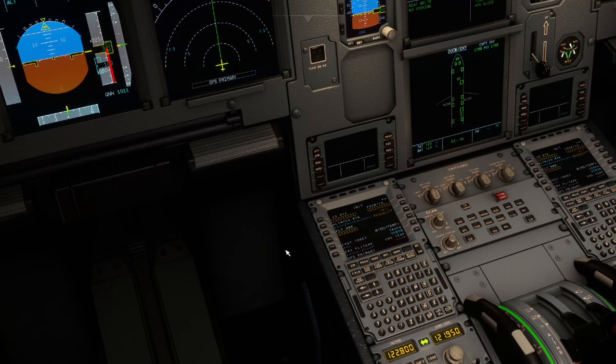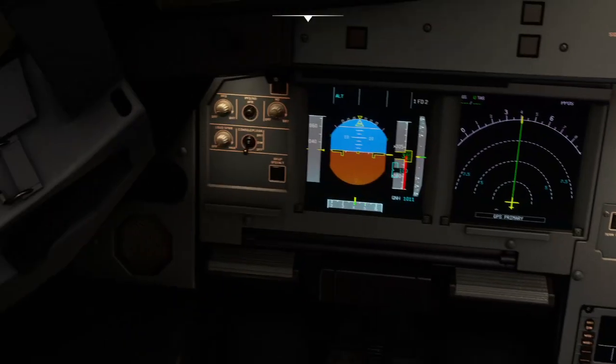So we've imported ourselves a SimBrief flight plan. Now we can just hit init request, pretending it's doing an ACARS uplink. It runs away and grabs our flight plan. Happy days. You can see the data is in: cost index 10, flight level 240 is already in. Take us across to the next screen. So we've got 4 tonnes of fuel, which is what I'm uplifting.